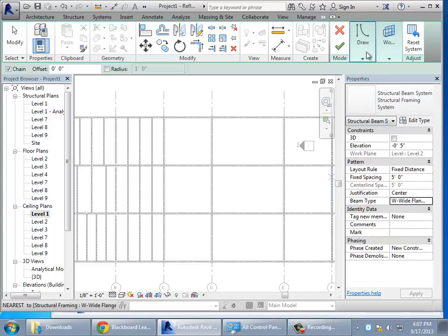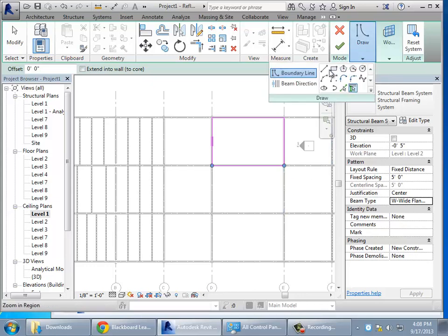So here's what it's going to look like. I can do some drawing, or I can do some selecting, since for many of the sides that I want to use as the boundary, I just assume they line up right with one of the existing columns or beams. I'll choose beam selection, so I can choose some boundaries over there. Whatever you can pick, almost like offsetting, whatever you can hang off another piece of geometry, do that. Now I have columns hanging off the grids, beams hanging off the columns, and beam systems hanging off the beams, so any stretching is going to be really resilient in following and adapting to whatever you do. But if you need to customize that boundary, this is what sketch mode is good for.